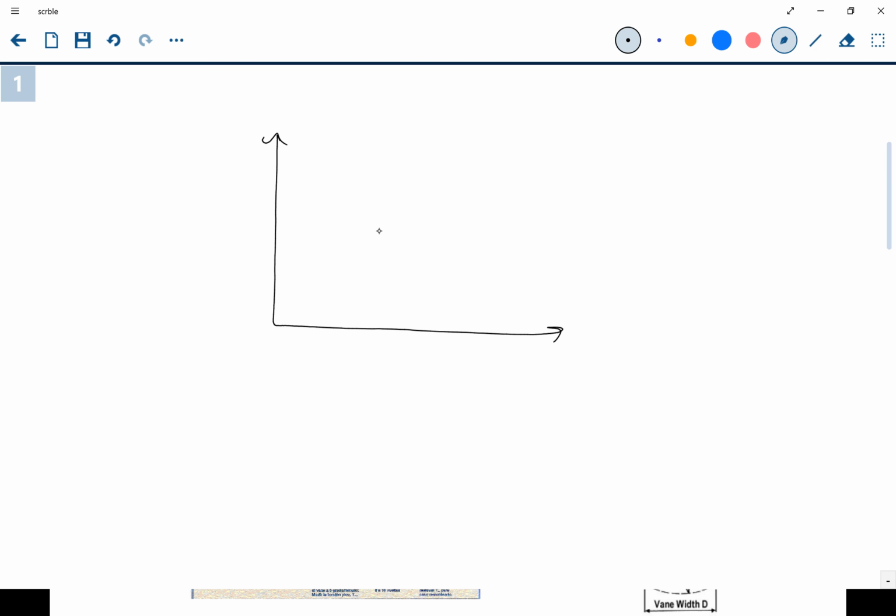if I were to take, say, SPT resistance, we often call this the N value, and plot that against the undrained cohesion of the soil, we would generally see a trend that might look like this. So there's definitely a correlation there, and researchers come and they fit lines to the data.